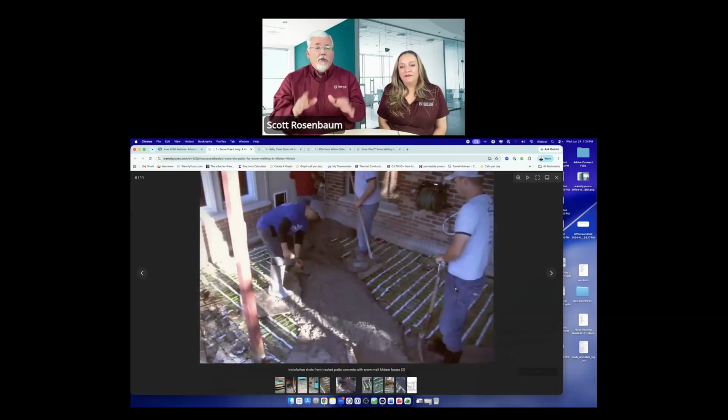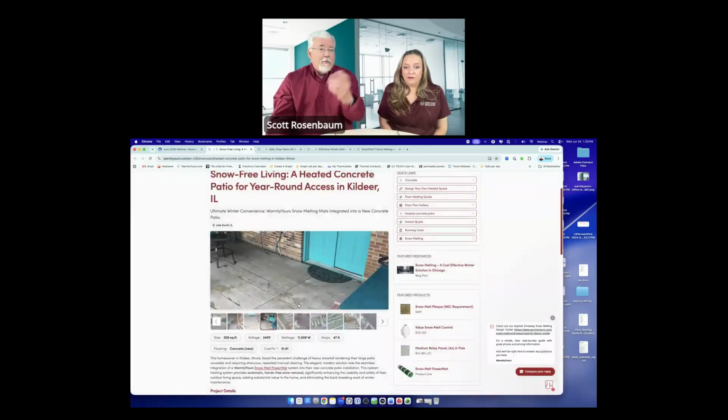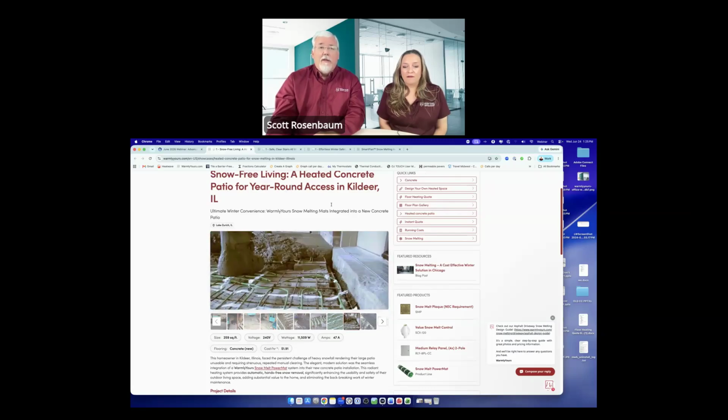So you can see what you're going to do in this case is this product has to be propped up on rebar, and they need to pour sub 3/4 inch aggregate concrete through this, because if the aggregate's too big, the aggregate will not flow to the bottom. Right. It'll act like a strainer. So we need to get that concrete, the whole mix, to get throughout the slab. So this cable is propped midway in the slab, halfway up, and it's a sub 3/4 inch aggregate that will pour through that and give you good results. So that's what a patio looks like here in the Midwest. And boy, that was a really fun experience putting that together.